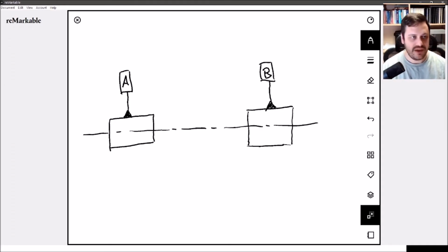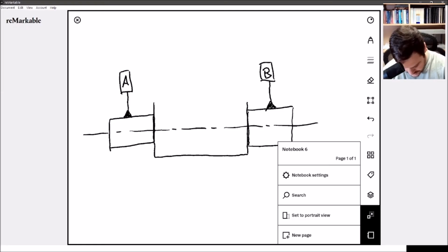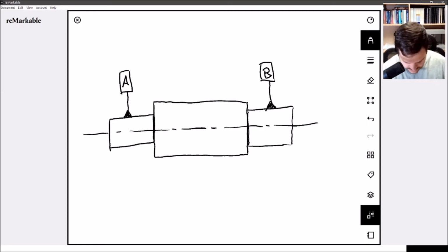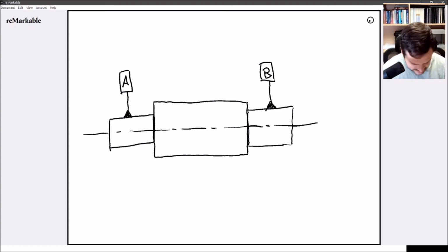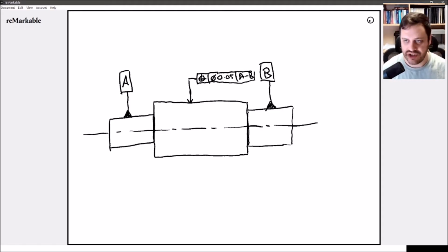On the drawing, I'm going to do this in two ways. First I'm going to draw how you would actually draw it on the drawing for your geometric tolerance. We come through to there, drop that down, and come across there. Apologies for bumping. So this is the notation to show our geometric tolerance. In this case, our symbol is like that. We've got our box, it's diameter 0.05, and then it's A-B. Close all that off, and that's how we actually implement that geometric tolerance.